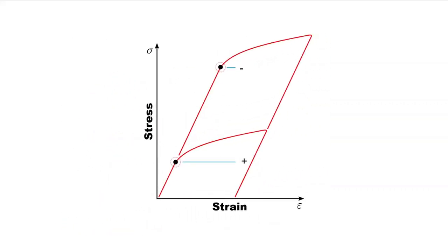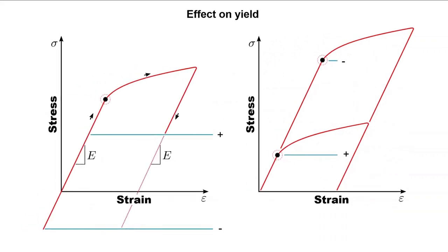If we were to consider the component to have zero overall strain prior to loading, then the net effect would look like this: a significantly higher external stress to yield for the region that is in compression, while a significantly less for that which is in tension. This is the effect on yield, as demonstrated by equivalent stress-strain curves. Therefore, consideration of what and where residual stress can manifest is important to some critical engineering components, as they will not carry their design loads without yielding in the worst case, and be over-designed in the best case.